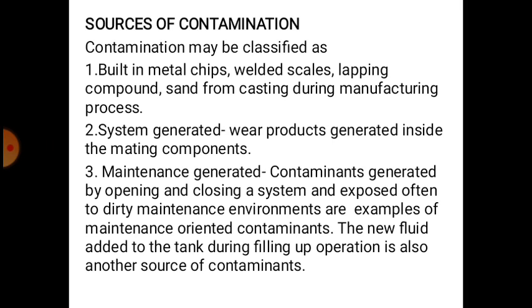Contaminants: the worst enemy of these precision-made components of a hydraulic system is the contamination in the fluid, which may be both solid and liquid. The solid contaminants are dust, dirt, worn out metallic pieces, and other particles. And the liquid contaminations are like water, acids, paints, etc. These contaminations are undesirable in the hydraulic system and therefore need to be arrested. There are different causes for failure of a hydraulic system, and the majority of them will be due to solid particle contamination in the oil.